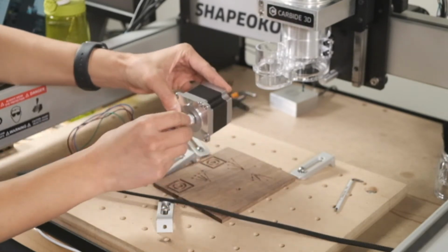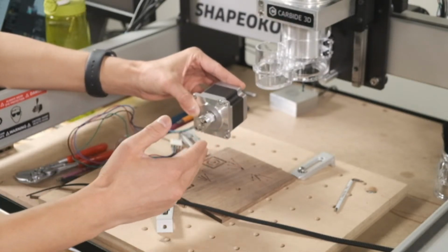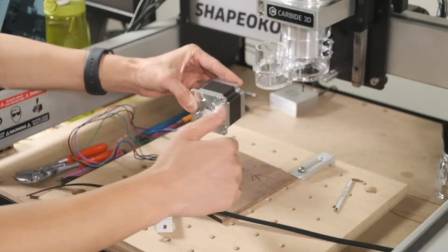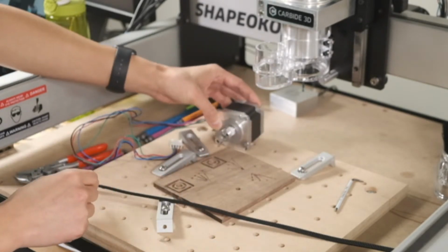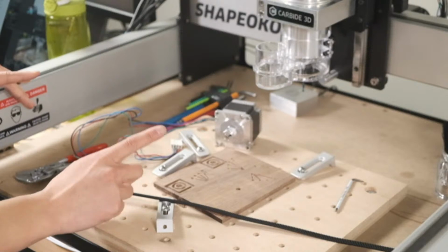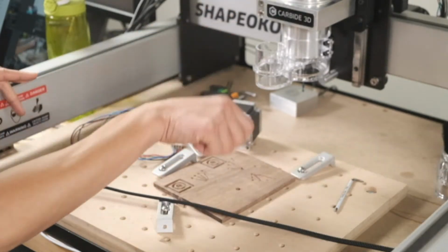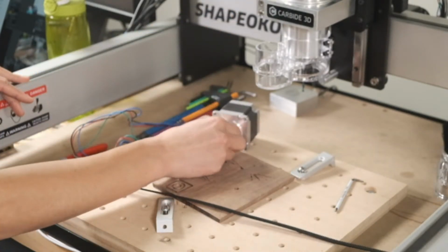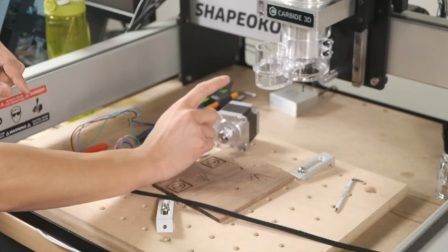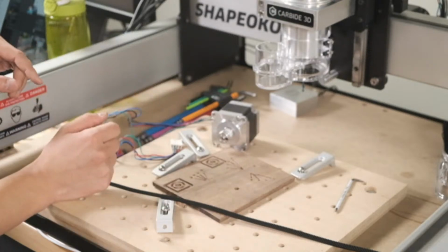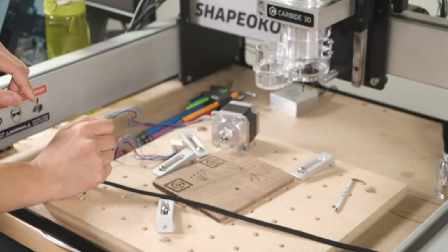So the X motion is always delayed, going in one direction or the other, or in Y, or perhaps in both, in which case you get a diagonally oval hole. So making sure you have tight belts and a tight stepper pulley is essential to making sure you get motion if the motor is turning and the controller is working. So that is probably the first place to look.